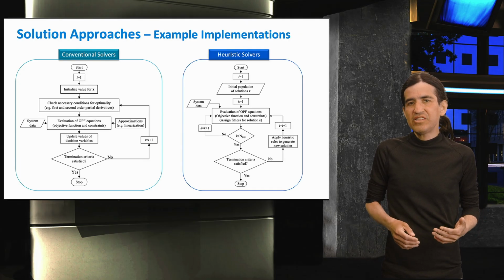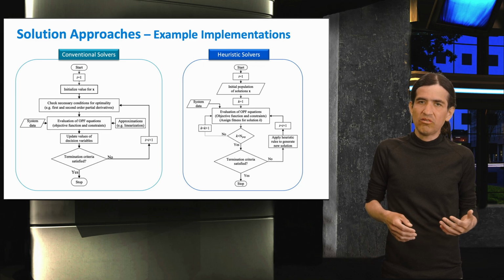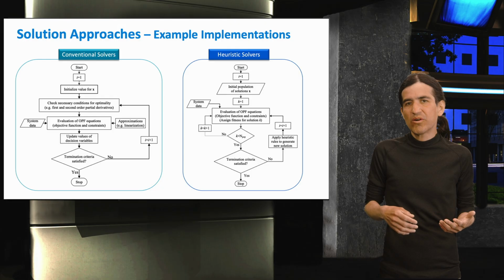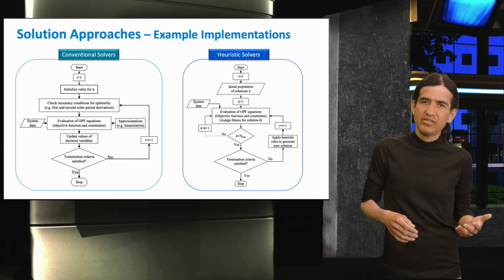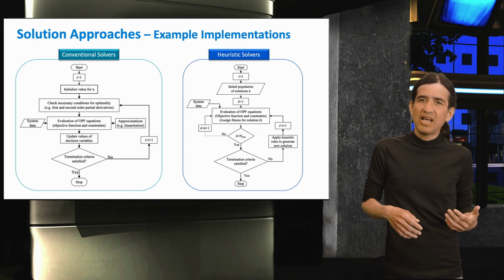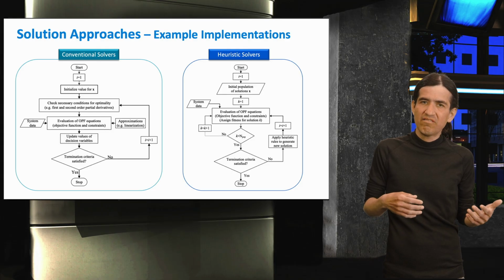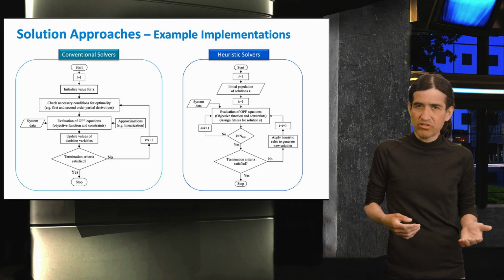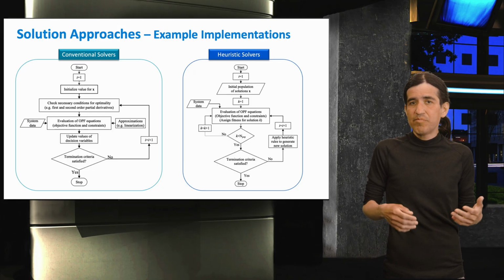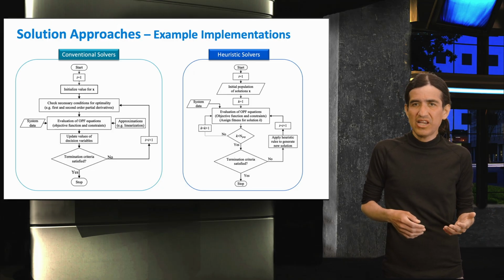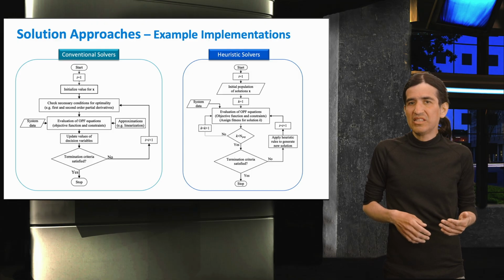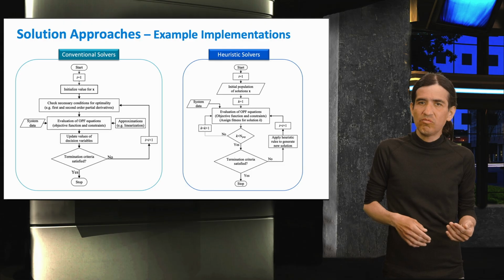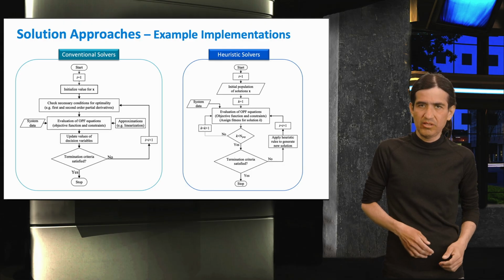Alternatively, a heuristic optimization solver, including meta and hyperheuristics, approaches the optimal power flow problem through a flexible, iterative search that does not rely on exact mathematical gradients, making it suitable for complex nonlinear and non-convex formulations. The process typically begins with initialization, where a single candidate solution or a set of candidate solutions is generated within the defined bounds.